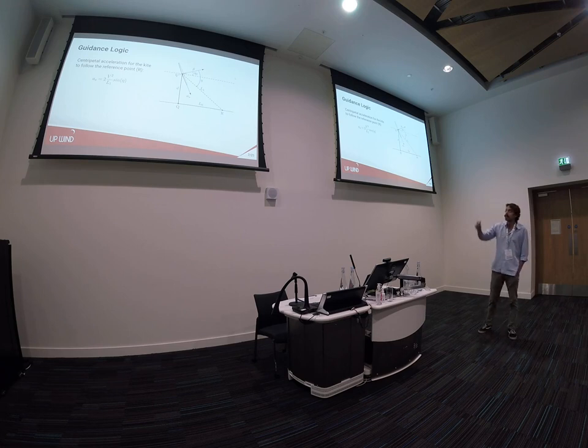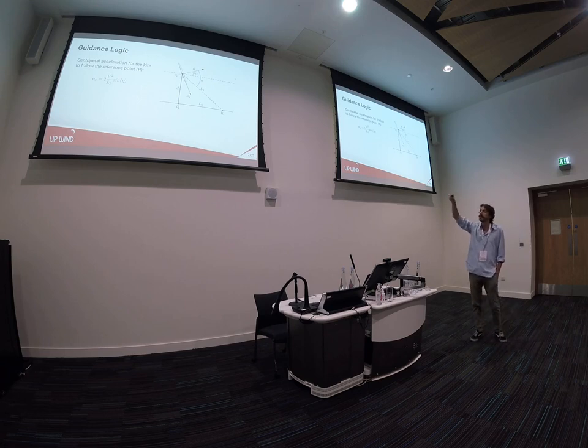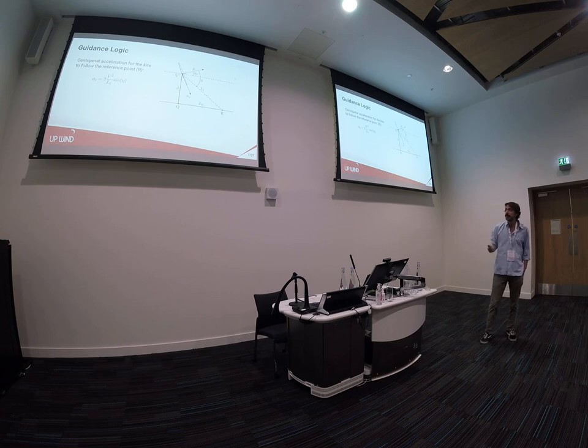Then based on that reference point R, we define L1, the vector between the kite position and the reference point, and from that we can compute the required centripetal acceleration for the kite to follow a circular trajectory joining the path in R. This is our guidance logic,